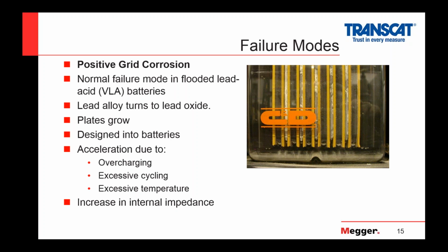In addition, the lead oxide crystals are larger, so the plates grow. If you look at the bottom of this image here, you'll see there's a gap between the bottom of the plates and the bottom of the battery. This is to allow for plate growth.